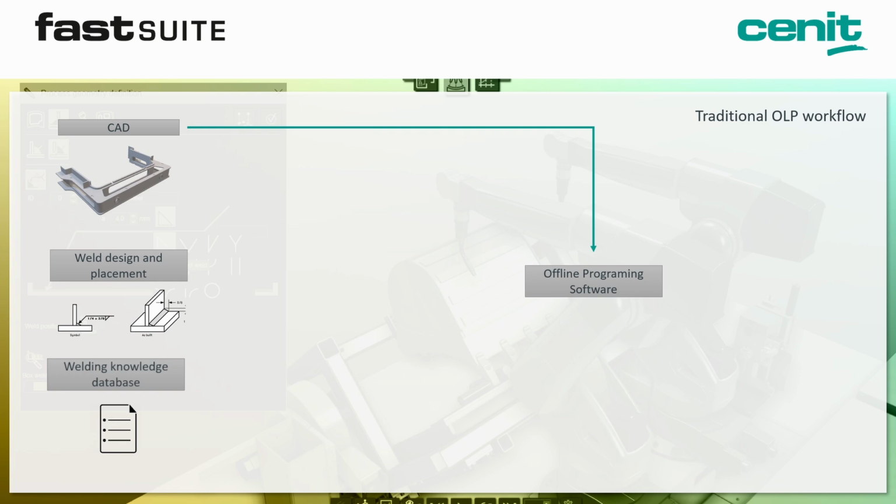Then we have to somehow match the design that we want for the part. We have to match these specific weld positions and weld sizes to the parameters that we want for each part of the welding equipment. Until now, even for offline programming, it is common for this process to be done manually. It is common that a robot programmer will take the CAD data, try to read some prints or welding schematics, and try to decipher, okay, we need a weld with these characteristics in this place.